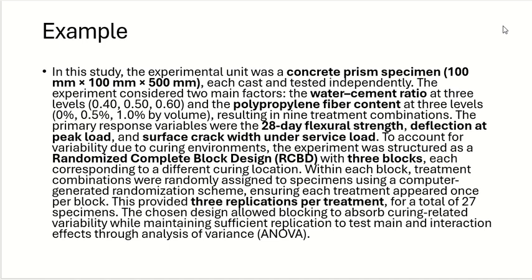How many response variables do we have? Flexural strength, deflection, crack width. Three variables. Service load is not a variable. Service load is the load you apply, the thing which will cause the crack. So it is part of the experimental conditions.